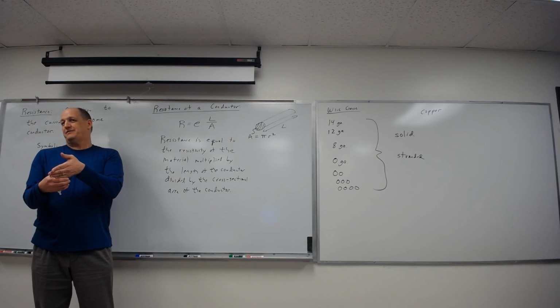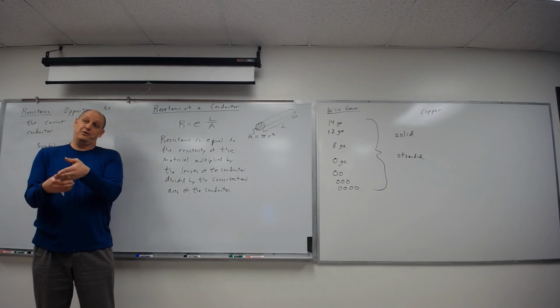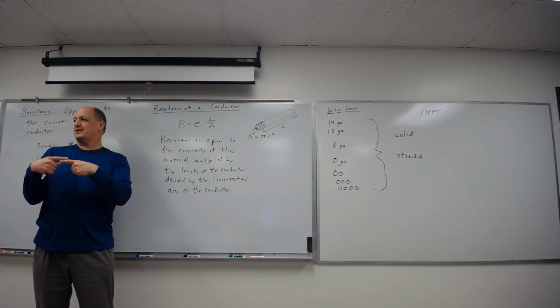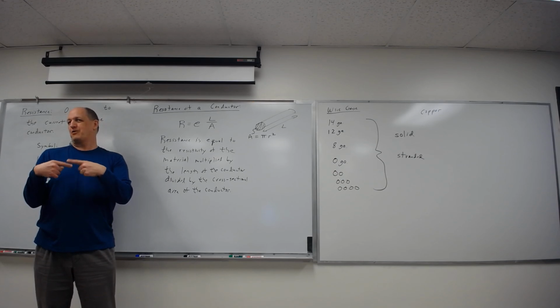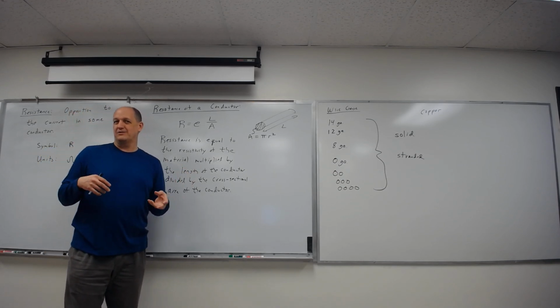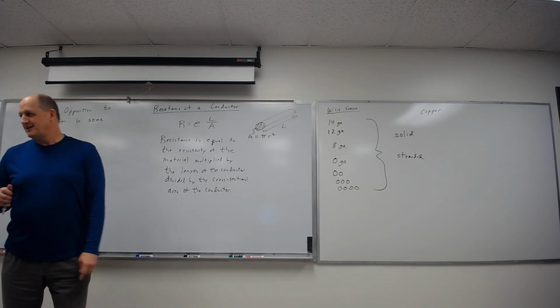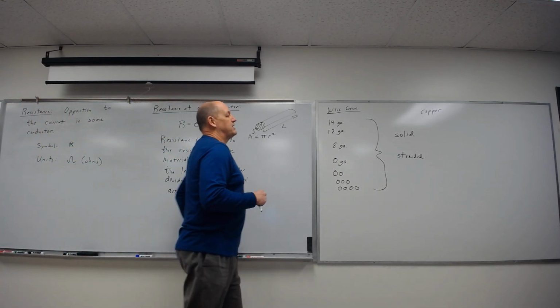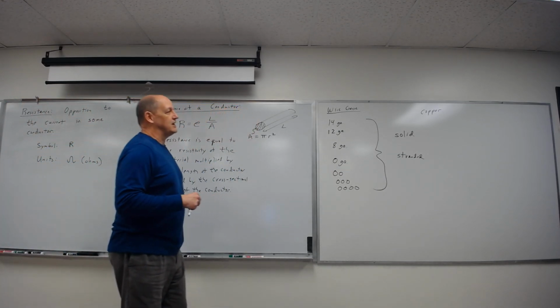We had a ton of them left over from preparation for World War II airplanes. So it's sitting around. We use it. It conducts well. It holds together well. It's strong enough. Unfortunately, it makes really weird connections with copper, so it's kind of a problem now. It also, when it overheats, decides to flame easier than copper, so it's got some issues. But yeah, we can use aluminum for all kinds of conducting.